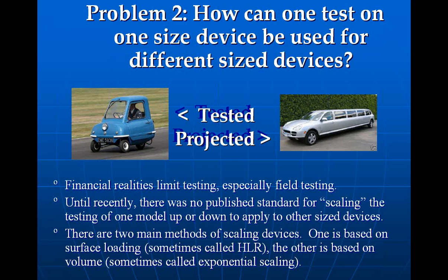But Dr. Minton convinced me in about 2004 or so that surface loading dominated the way particles came out of devices. And the long story made short, when I went to the city of Marietta, we came in with a published scaling. We said we're not going to load it at over 31 gallons a minute per square foot, something like that.